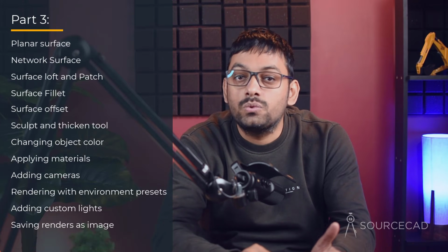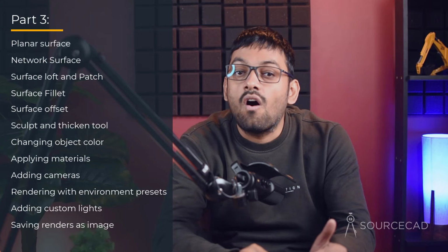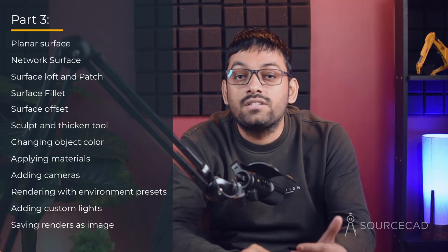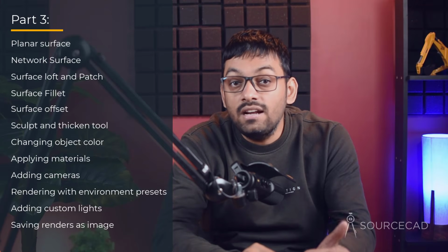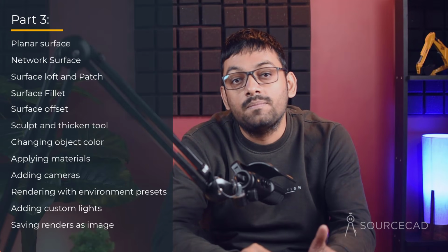We'll start with surface tools like planar surface, network surface, surface loft, patch, surface fillet, offset, sculpt, and thicken tool. Then we'll talk about visualization tools like changing object color, applying materials, adding cameras, rendering with environment preset, adding custom lights, and finally saving rendering as image file. So with that, let's get started with the surface tools of AutoCAD.